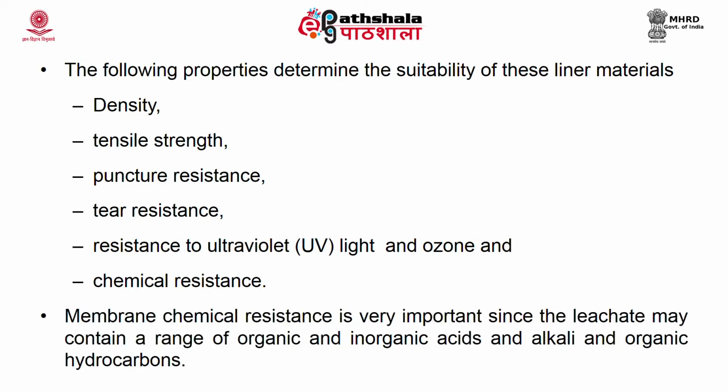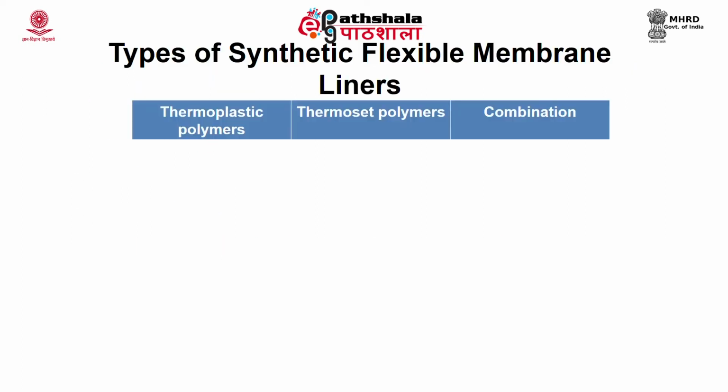The membrane chemical resistance is very important, because as I told you, the waste material contains a lot of organic and inorganic acids, alkalis and other organic hydrocarbons. So, you have to be very careful when you choose the type of flexible membrane. Now, this table summarizes the types of synthetic flexible membrane liners which are popularly used in a